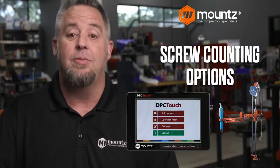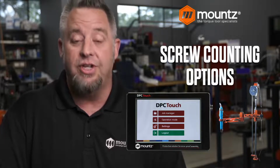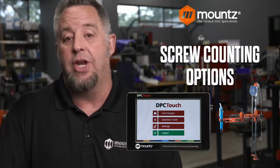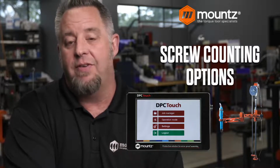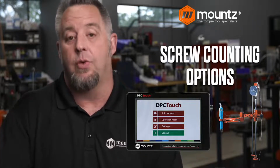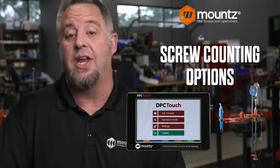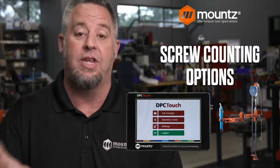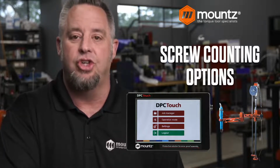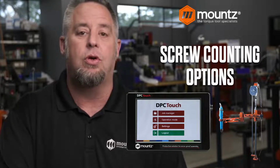With the DC system, it allows the location to be controlled, the preset that is being used. So we do have that capability where every fastener that gets torqued is done correctly, and the system won't index to the next location until we get a good rundown signal back from the tool.